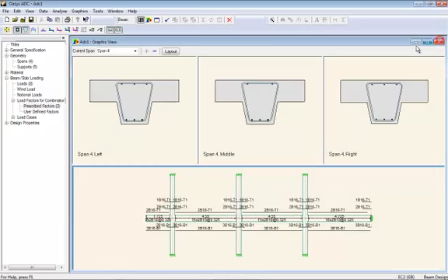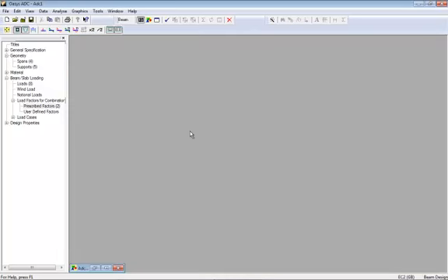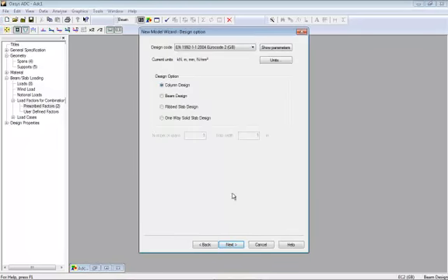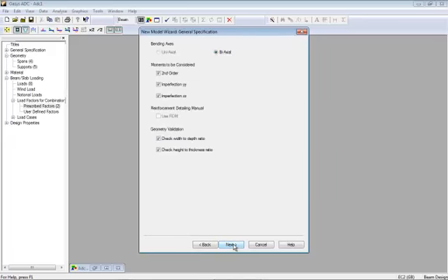Now the column design is slightly different in that for the column design, first of all, you've only got one single span, but also it does additional things such as when you apply an axial load, it will add on moments onto the column from the second order effects and the imperfection requirements, or the eccentricities, depending on which design code you're working to.